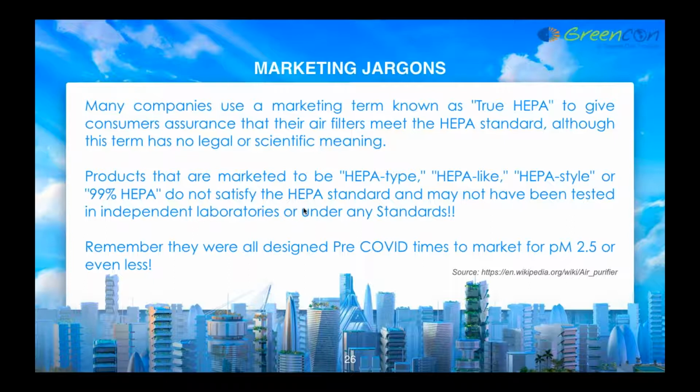All across the globe, there was a requirement to take care of the outdoor air. So you need to size up the purifying system to understand what you are targeting. Are you targeting PM 2.5? Are you targeting smoke, VOCs? You require different kinds of systems to handle those kinds of situations.